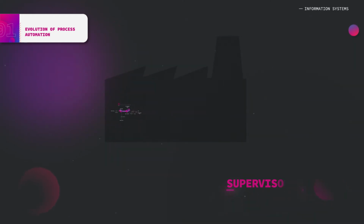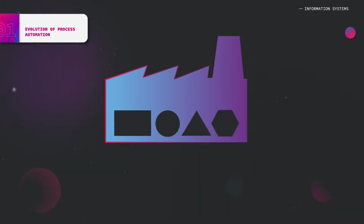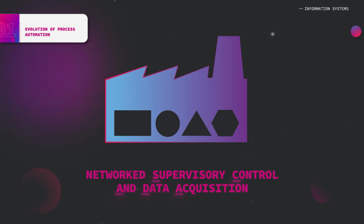These systems were generalized to the entire power plants through distributed SCADA systems. Then, with the launch of standards, SCADA systems became interoperable whatever the brand. It is named Network SCADA System. The emergence of cloud computing and Internet of Things slightly changed the architecture by transferring local infrastructure such as server, database, remote terminal units, or even programmable logic controller to distant servers and calculation facilities operated by services companies. This new structure permits distant monitoring and control.